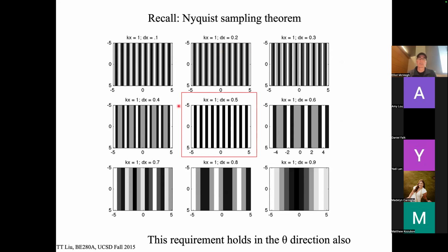As I drop my sampling rate, we found that the rate required to reproduce this signal well was called the Nyquist criterion. I needed basically 2 samples per wavelength: 1 up, 1 down, 1 up, 1 down. So whatever that period was, I needed 2 samples per that period to hit the Nyquist criterion, such that I could render this sine wave without bleeding in energy from higher frequencies, etc. Okay.